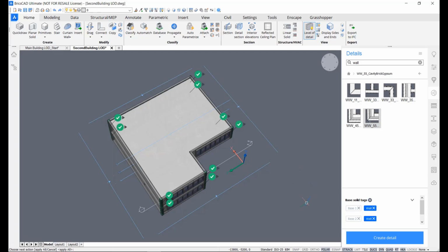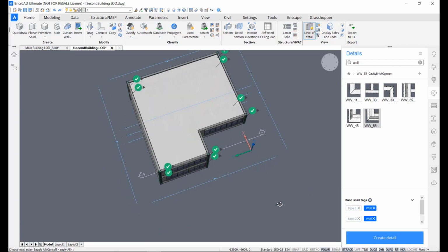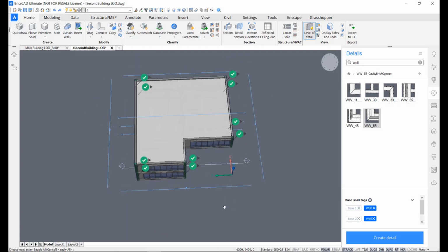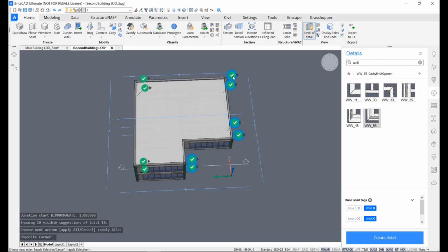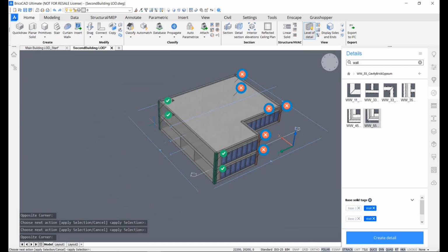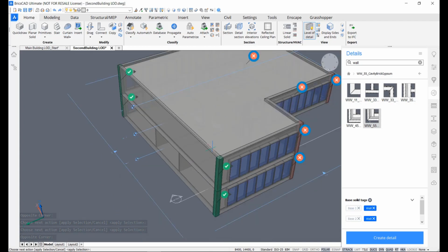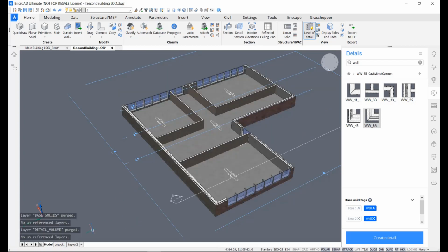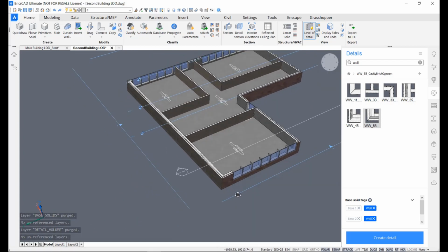In this case, I just want to have this connection for the wall connection, which is the wall front and the wall back. So we can check off the rest, which are the front and front wall, like this. So only the blind wall should have this kind of connection. Enter. Apply all. And you will see it will be applied to 6 connections like this.